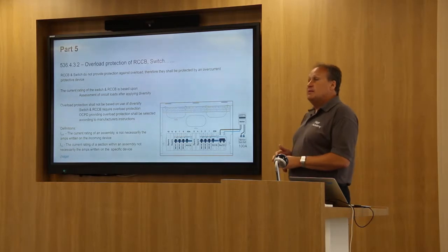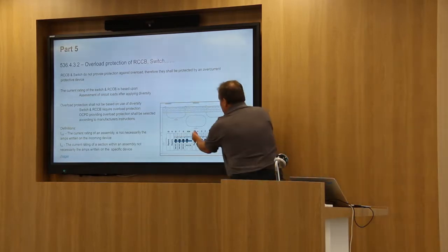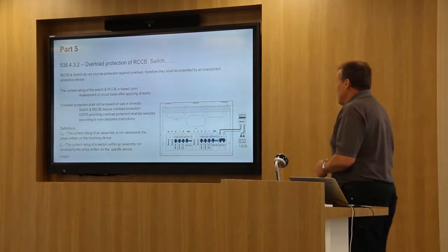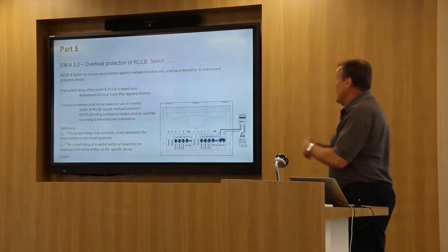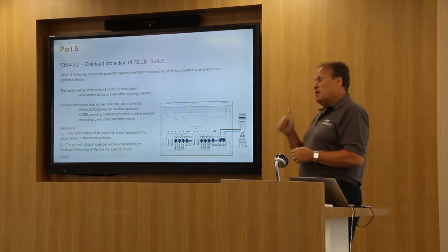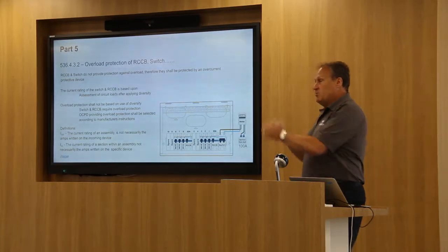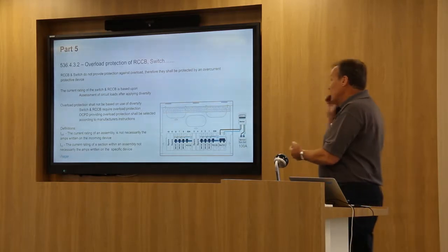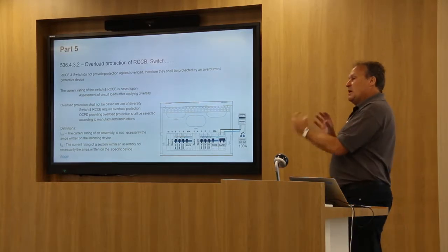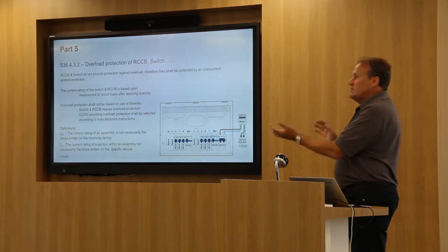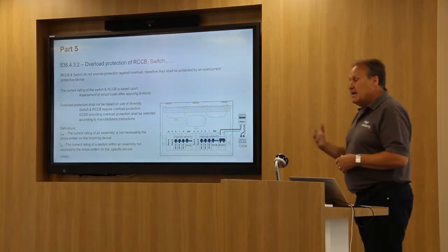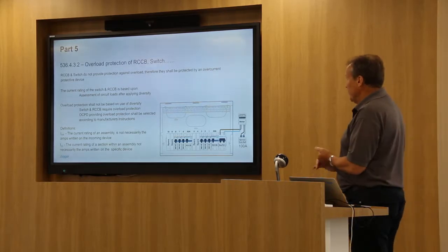INC is a section within the assembly, so it may be this section here. The RCCB with its MCBs after it is a subsection within that assembly. That again will have a current rating. Okay, not necessarily because it's got 63 amp on the RCCB. Can it be 63 amps once it's enclosed in that assembly? We're kind of used to the concept of changing the rating of cables when we enclose them. It's the same concept. If we enclose products, be they cables, be they RCCBs or switches, we may have to change their rating or derate them slightly.